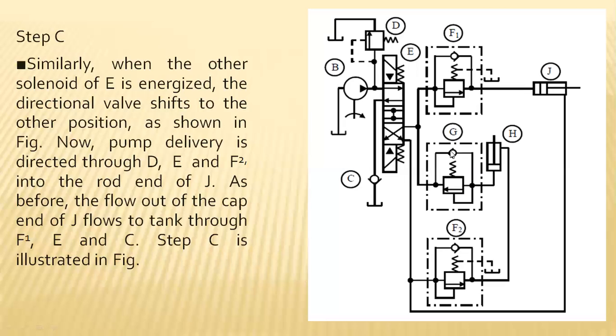If there is any free flow like this in the F2, directly the speed movement of this piston will take place in the retraction stroke. So to oppose that particular pressure, and to operate the safety conditions in the system, if the pressure is obstructed with respect to a check valve, the same pressure which is being maintained will be imparted with respect to the compression in the spring.